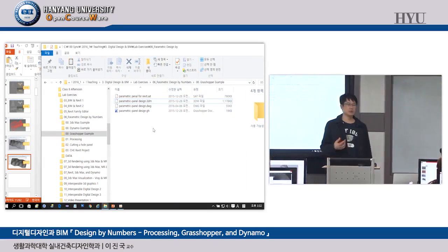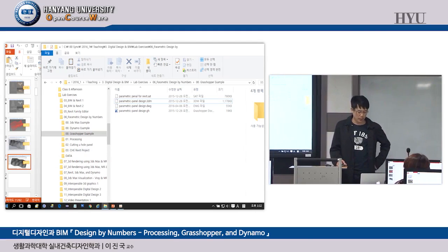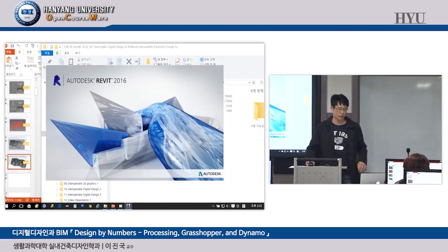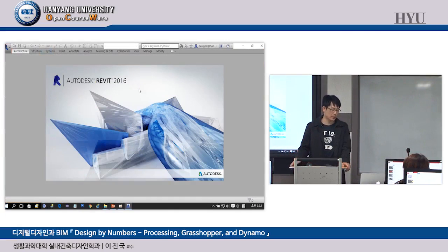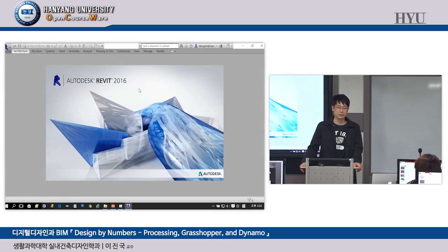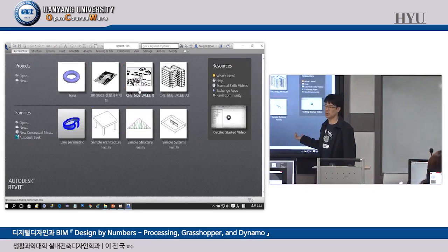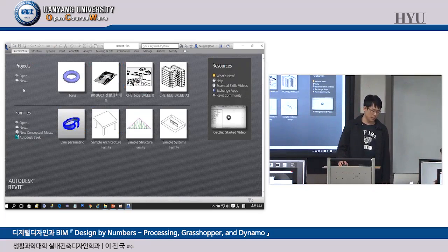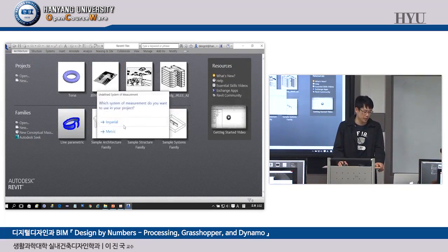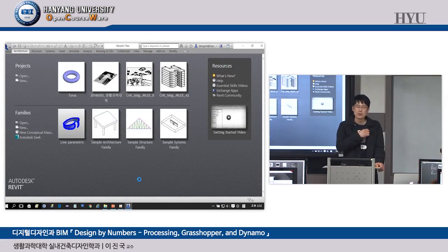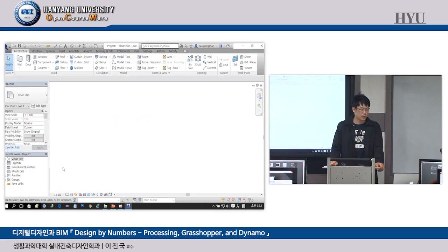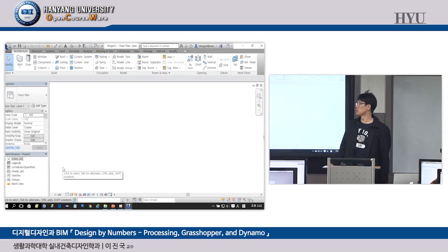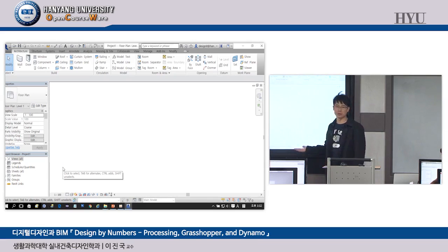Next thing we need to do as a live demo is, just for your information, I'll let you know the difference between solid 3D and surface-based 3D using Revit. So please open Revit, okay? Open Revit, click New Project, New Metric Project, which means please open an empty, blank Revit project, okay? And I'm going to import geometry, okay?